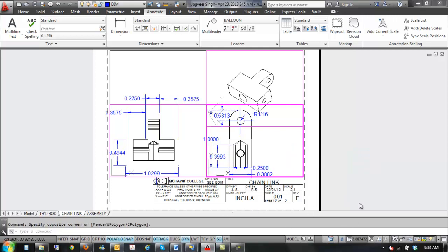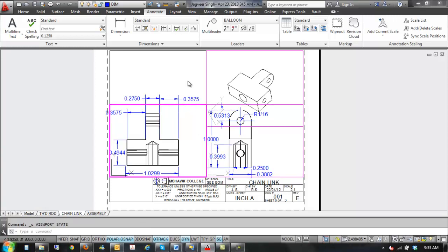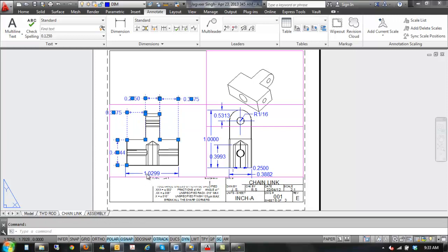Now, actually, I'm going to go back because I see your dimensions are done in paper space rather than model space. They're unrelated. When we're working on the thing that's eventually going to be printed, we're working on our layout down here, right? If it's related to the model, like the dimensions are, they should be in model space. So I'm going to undo my scaling, and these dimensions that you have, which you may end up wanting to redo, I want to push them back in the model space.